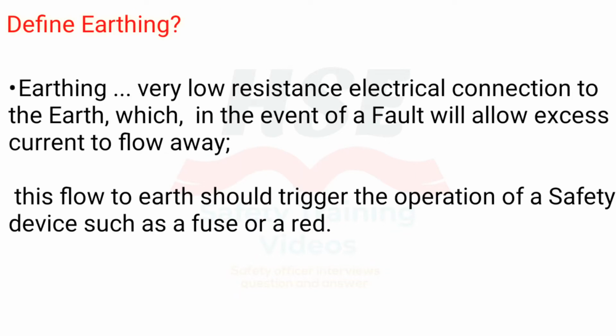Define earthing. Earthing: a very low resistance electrical connection to the earth, which, in the event of a fault, will allow excess current to flow away. This flow to earth should trigger the operation of a safety device such as a fuse or a RCD.